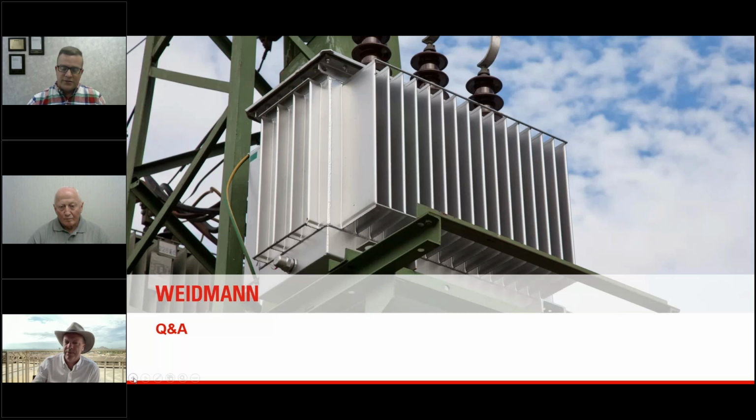No, that's a really good question. So we actually have several coated papers that we offer at Weidmann, several grades of base paper that are still coated in the same process and with the same epoxy resin dots. And so really the base paper is independent from the bonding and curing of the epoxy dots. So in fact, DPE is going to cure in exactly the same way as all of our other coated papers, again, because the process of coating and applying the epoxy dots is the same process.